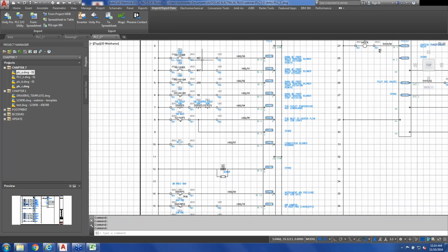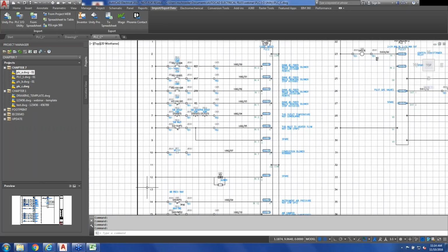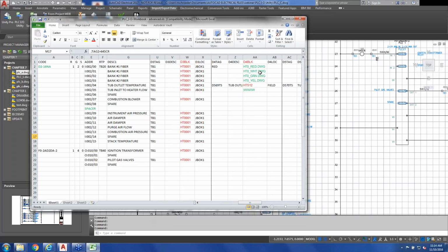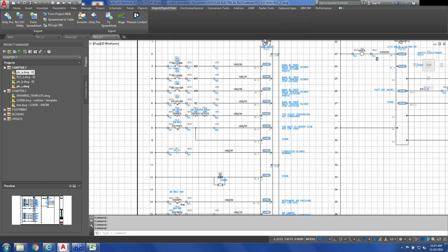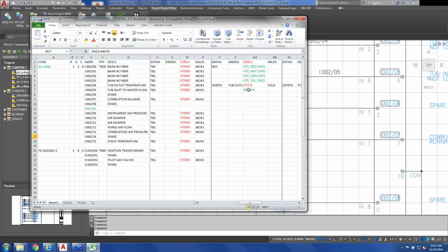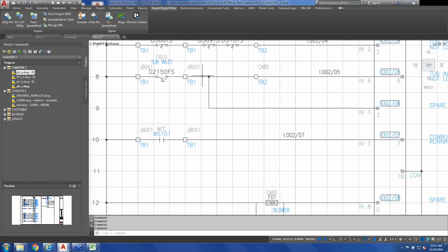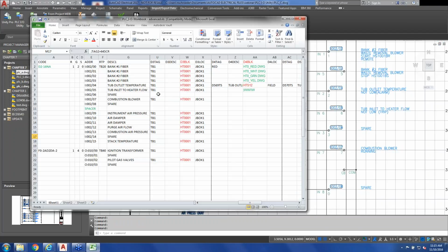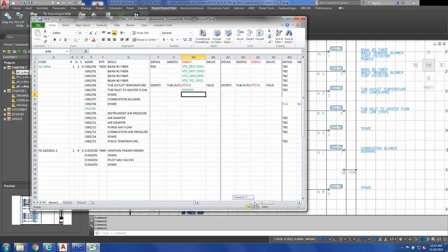So you can see here I have added some inline devices. My spreadsheet is pulling in my cable color blocks that I've specified here, and then that jumper is showing up with the WWXW, so it kept this wire to the left and to the right to the top, trimmed the wire to the bottom left, and kept the wire to the bottom right. And that's between the 5th and 6th addresses here. So between the 5th and 6th addresses is where it created that jumper wire.